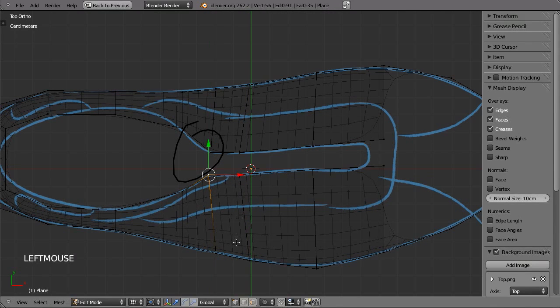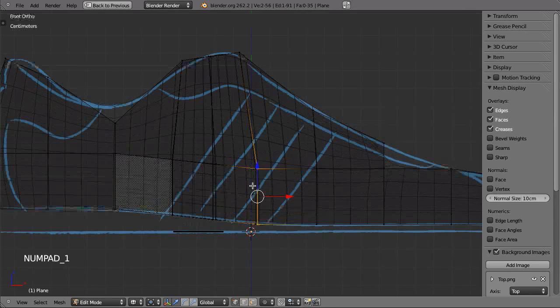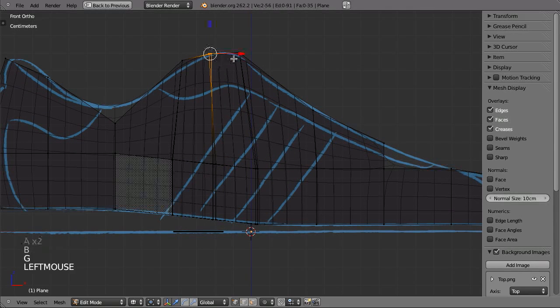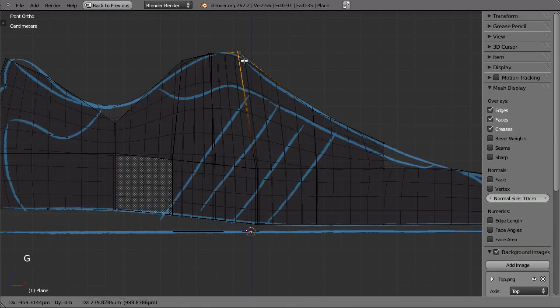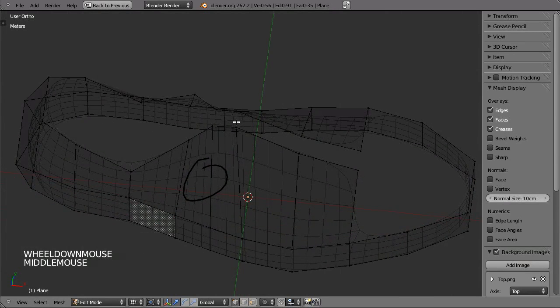And also when you add loop cuts, keep in mind, for example, that this section got more straight now because the amount of vertices is denser. So try to keep an eye on that and, if possible, even out the curvature a little bit. I do this by spacing out my points just a little bit. Up here I keep them the same, because there I need them to be close to each other so I can get that tight change inside the profile curve, but here I don't need it.